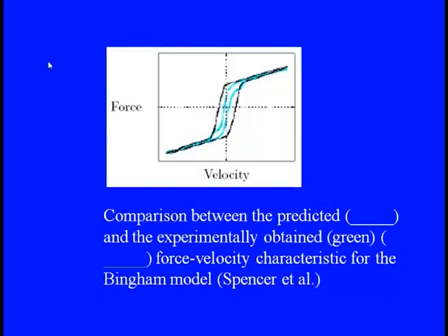So, these three equations formed by the Bouc-Wen model simply show the relations of all these parameters when the entire fluid damper model is behaving under the excitation force F. And when we try to compare the experimental and the theoretical predictions in the Bingham model, as I showed, this is my hysteresis slope. The experimental features clearly show the nonlinearity, as you see in the green part.